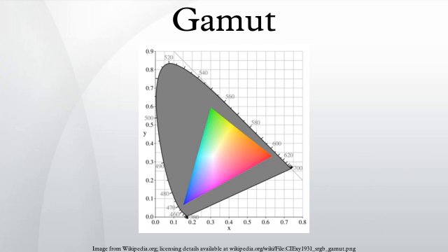Systems that use additive color processes usually have a color gamut which is roughly a convex polygon in the hue-saturation plane. The vertices of the polygon are the most saturated colors the system can produce. In subtractive color systems, the color gamut is more often an irregular region. Comparison of various systems: following is a list of representative color systems more or less ordered from large to small color gamut. Laser video projector uses 3 lasers to produce the broadest gamut available in practical display equipment today, derived from the fact that lasers produce truly monochromatic primaries.